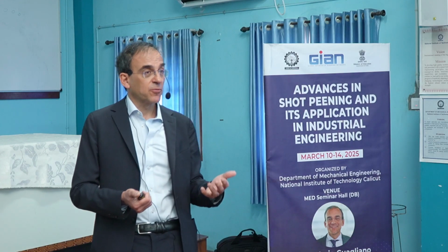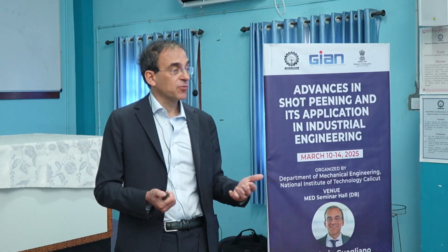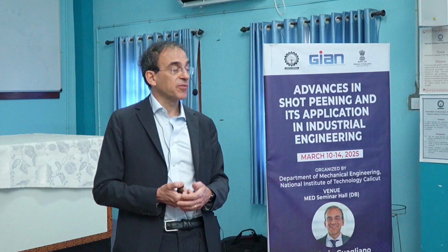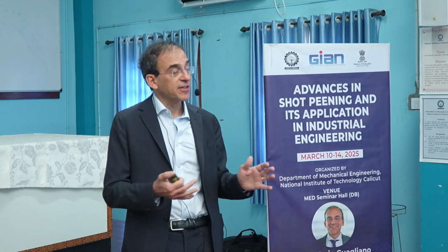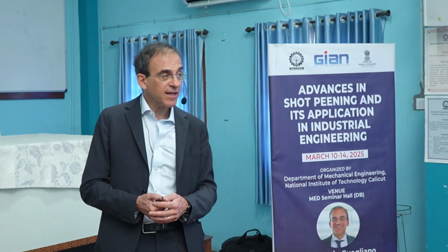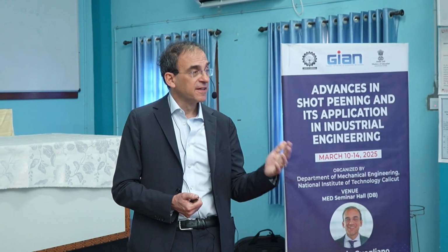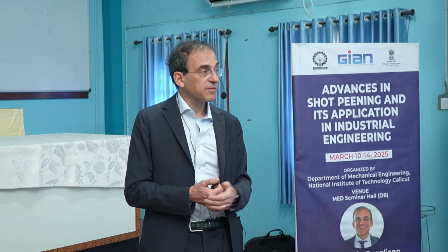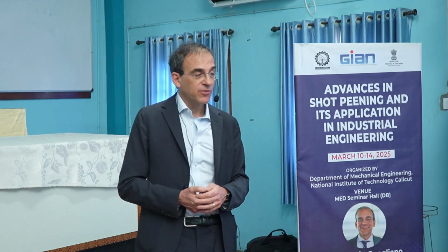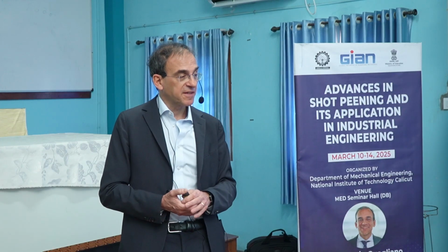Why? Because of the internal defects they have, and the quality of the surface is not enough, at least for structural application, for fatigue application. And so some post-treatment is needed, and shot peening is one of the possible post-treatments we can use for improving the fatigue strength.